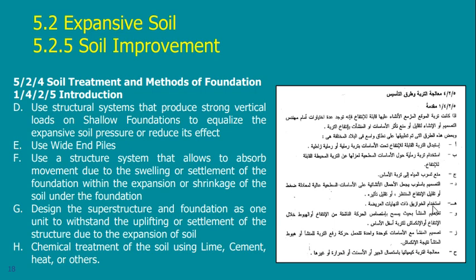The other is to use, say, piles, to change the foundation type. If I change the foundation type, maybe I would use a better type of foundation. Piles are not good for expansive soil, because once the soil expands, it may crack the piles, because the expansion is very high, and it may induce horizontal forces on the pile and crack it. So the best thing for this type of soil is to use either shallow foundations or raft foundations with openings to relieve the pressure of the expansion.